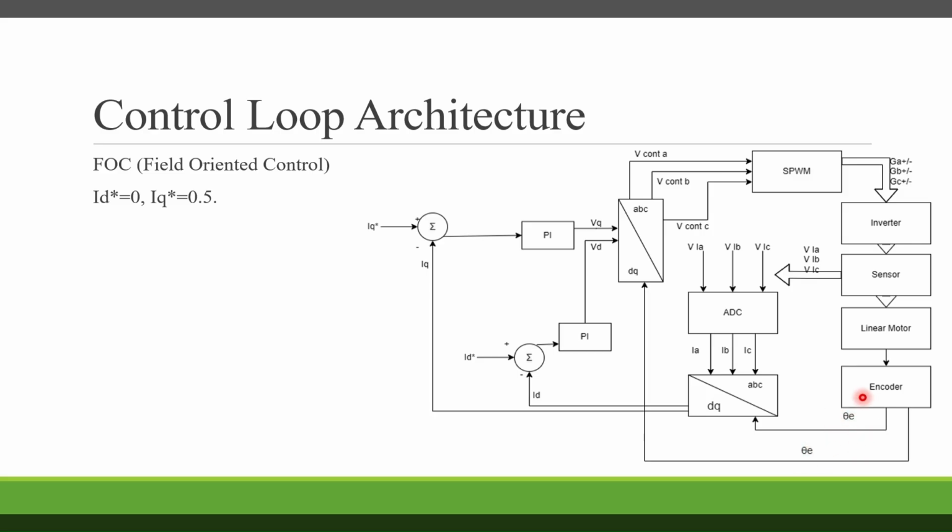In effect, I want to add an angle delay to theta E. By adding an angle delay, I can match the degree in this transformation, so probably moving the D value and Q value back to their intended position. Maybe this will solve the problem.